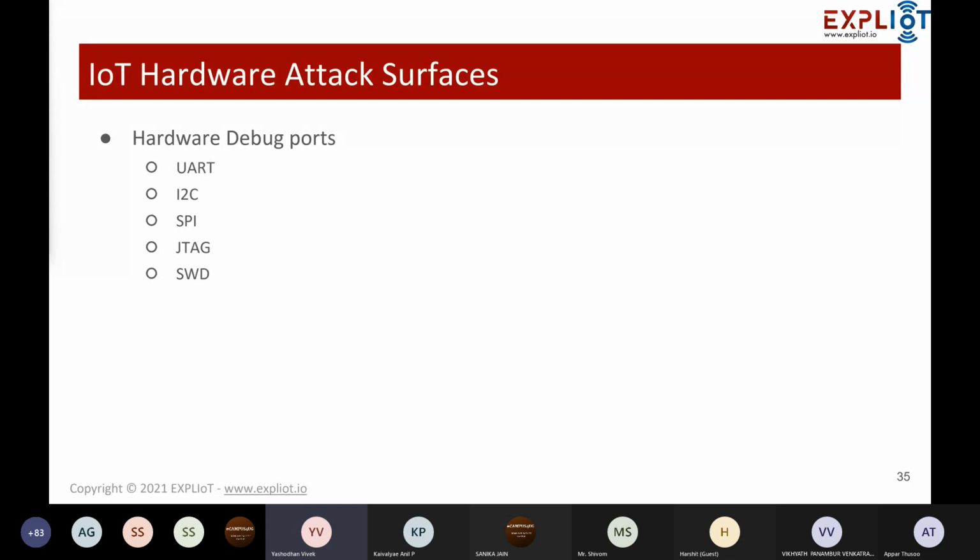And again, from the product development perspective, when you have a large number of units to be manufactured, like 10,000, 20,000 or 1 lakh quantity of IoT devices, you need a process where the production people should be able to debug things once production is done. For that, we have the JTAG and SWD interfaces on a microcontroller. It started late from the AVR series, but most ARM technology comes with these inbuilt JTAG and SWD ports, right? These are the typical hardware debug ports.